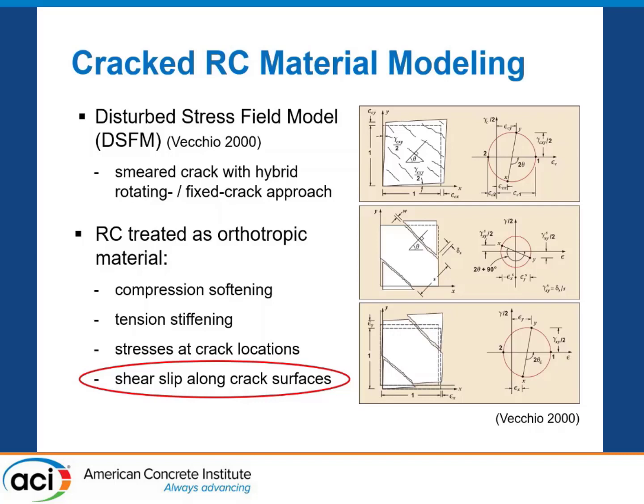So it does a specific examination of what's going on at the crack, and this circled point I have here on the bottom, the fact that it accounts for shear slip along crack surfaces, this is really the primary differentiator. There's several things, but I would say this is the main one differentiating DSFM from modified compression field theory.